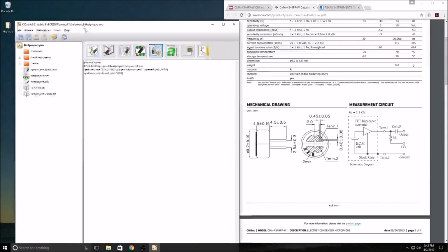You can put those all into a folder like that. Make sure you have all of the files here, because if you don't send all of them, they won't make the whole thing for you. And then there's another drill file here. So we have the drill file, we have all of our stuff here. And once we have that all done, we make that into a nice zip. And then basically you just upload it to your favorite manufacturer house, and they'll make it for you. So that's pretty much everything that you need to know in order to get started on KiCad.